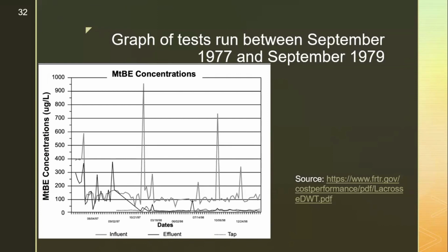These values only really spiked when the influent spiked, and they ran additional testing and found out it's because they used primary well 5 for the majority of the time, and then on weekends they swapped to primary well 6 as a backup just to give well 5 a break. And they found that in well 6 there was a higher concentration of all the chemicals that they were trying to get rid of, which led to the higher results after removal. They decided to decrease from taking 20 hours of water a week from this well to about 4 or 5 to help avoid this problem.